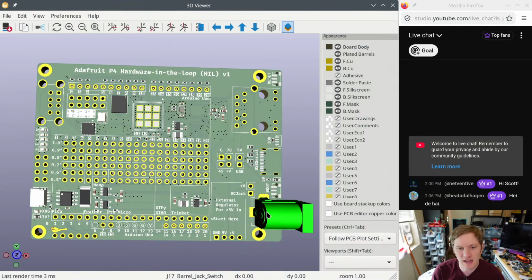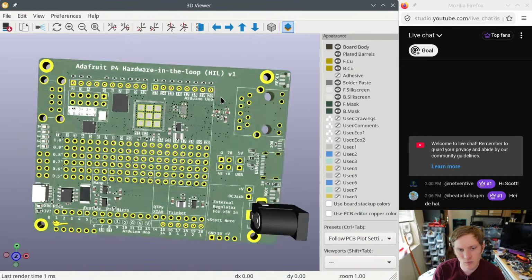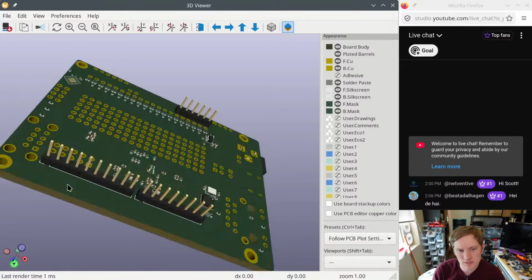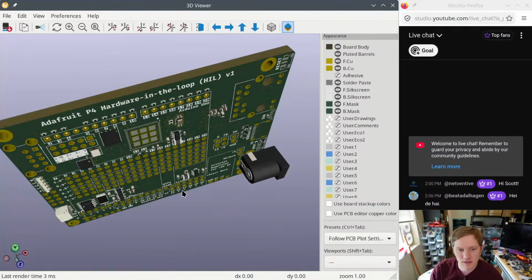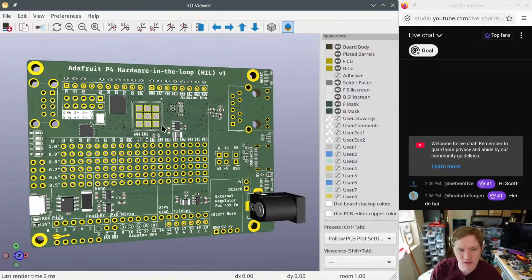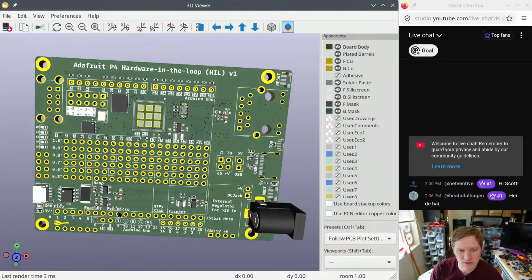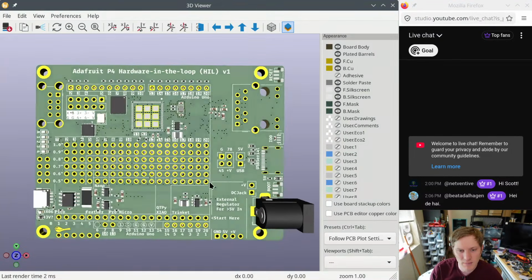And to that end, since I always want it plugged in, the interface chip here for the Ethernet can actually do wake on LAN detection. It's shared with the NeoPixel, but if you go to sleep, you can have this wake you up if you configure it right. So that's something that maybe if we do have a lot of these, we'll end up doing. And then I have power options as well.